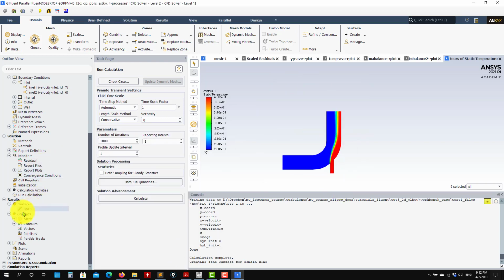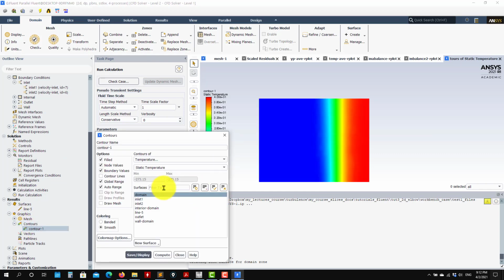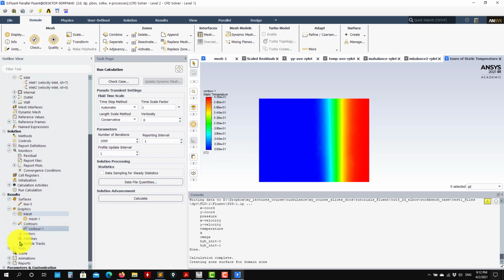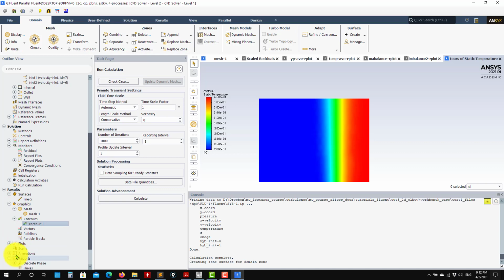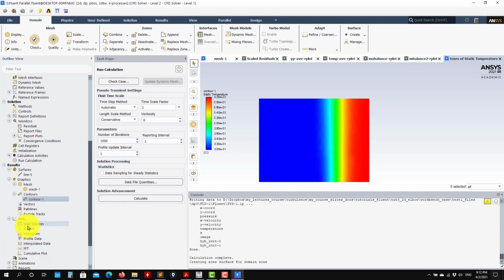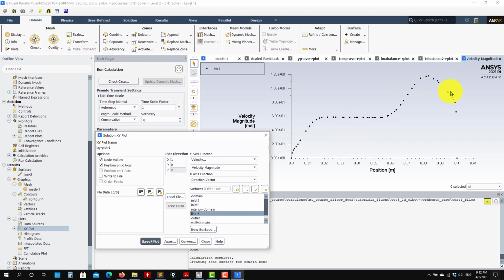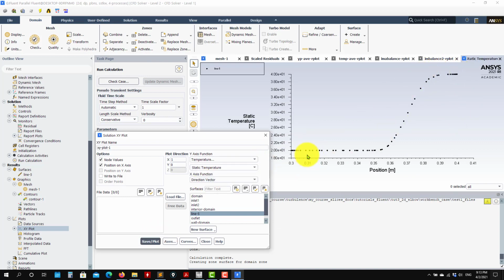So now you can also access all your properties, turbulence model, everything, you have it there. So if, for instance, you want to plot in this line, you go plots, sweep plot, pick up the line, and for instance velocity, and see this is the velocity profile along that line. So here you can clearly see the secondary line.